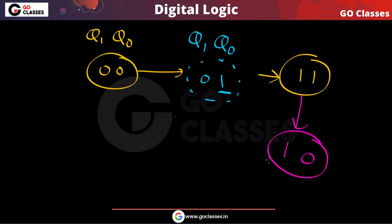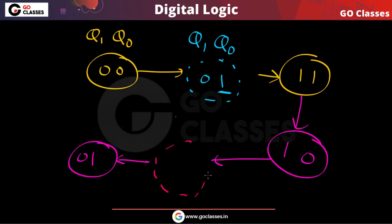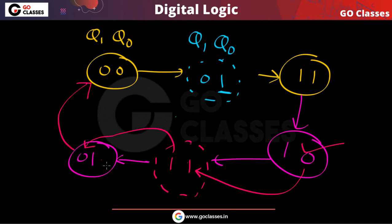Now from 1 0 you will go to 0 1. But you can notice they will not change simultaneously. For a small moment, first q0 will change, and then q1 will change. Then from here you can go to the next state because q0 can change. So I hope the idea is clear to everyone.